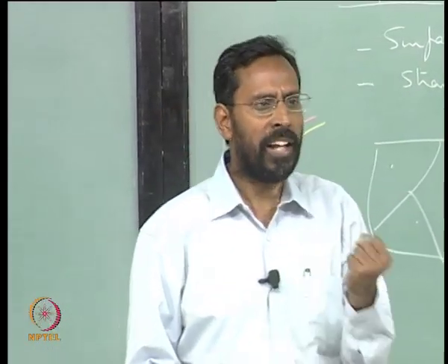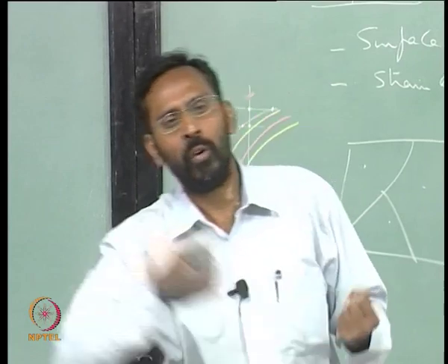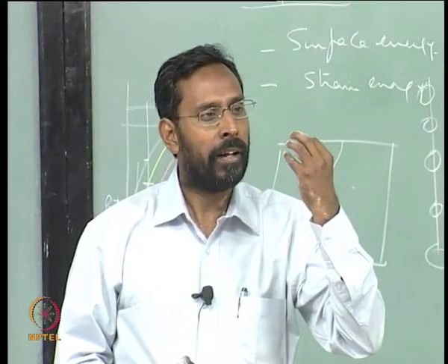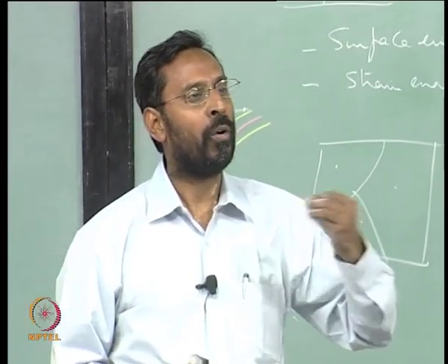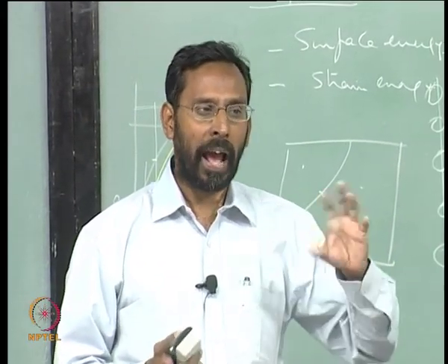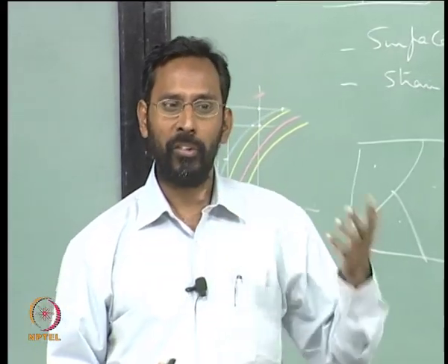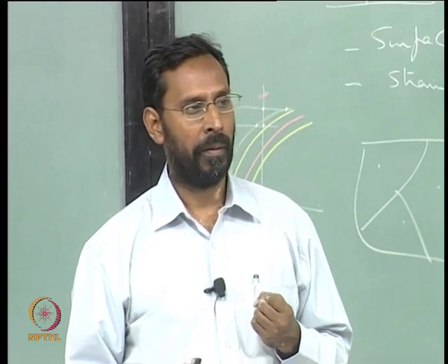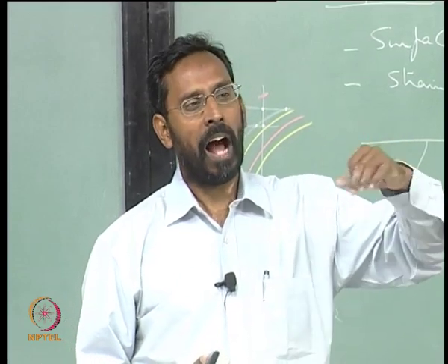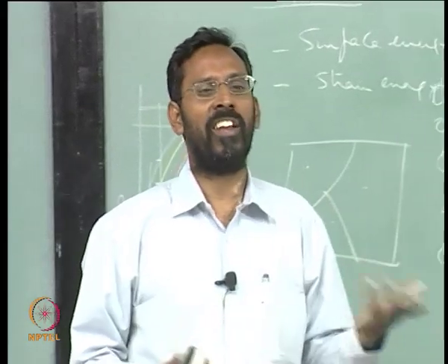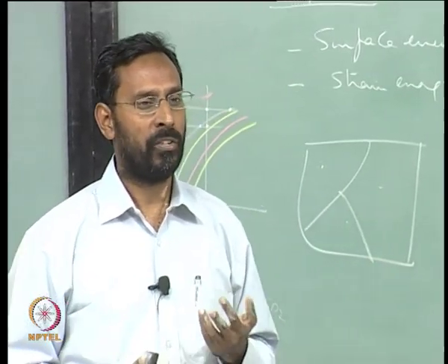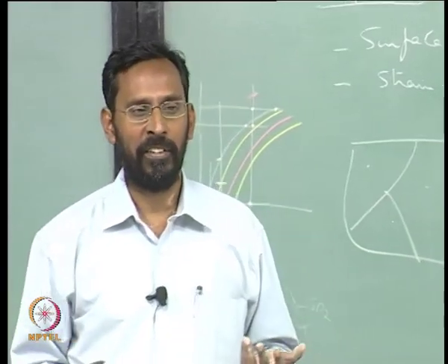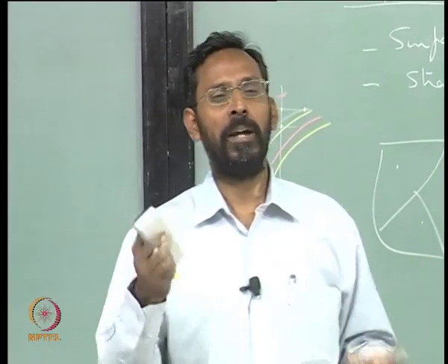The system is already in a lowest energy state, so it does not want to create a new surface. So the stronger are those alloys which have coherent precipitates. But again there are other issues coming into the picture. Coherent precipitates, being very small, can also be sheared because the size itself is very small. So the total area that you are creating when you are cutting it is not very large. So you have to look at weighing both the cases.